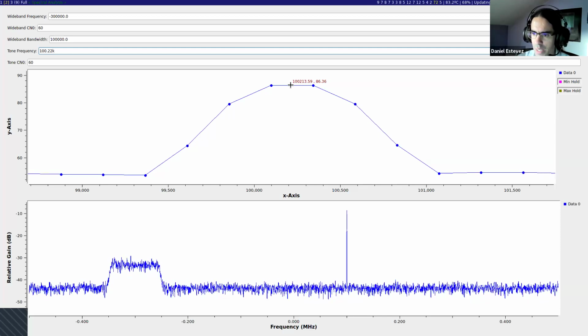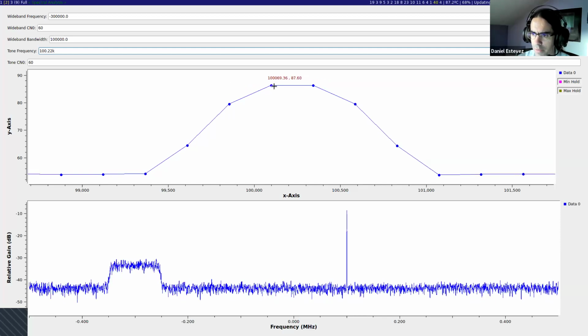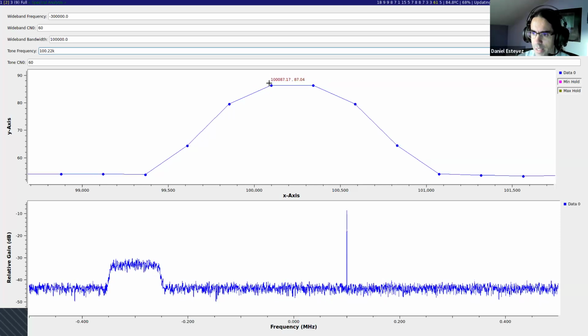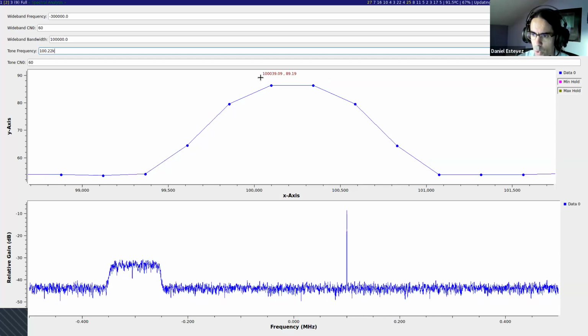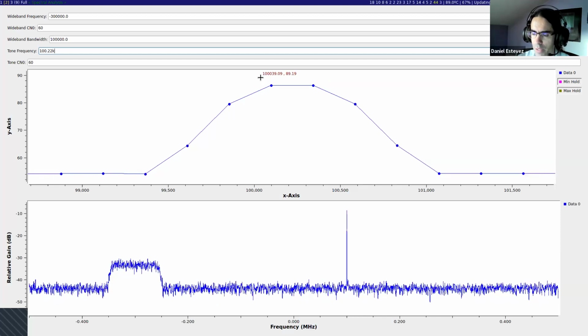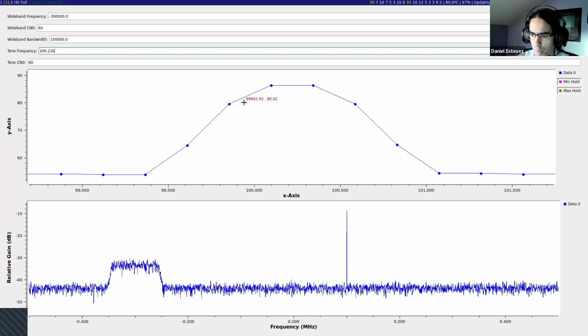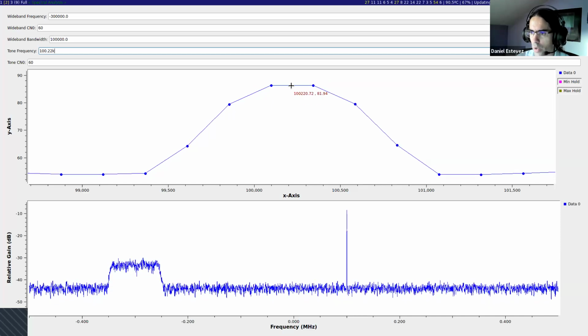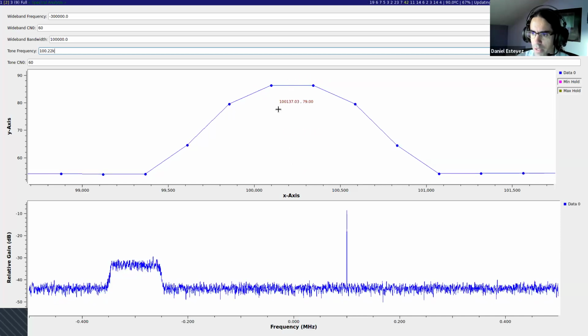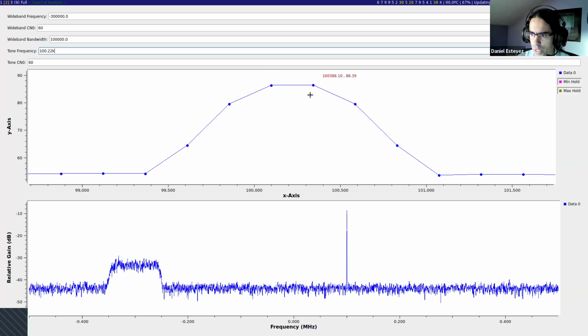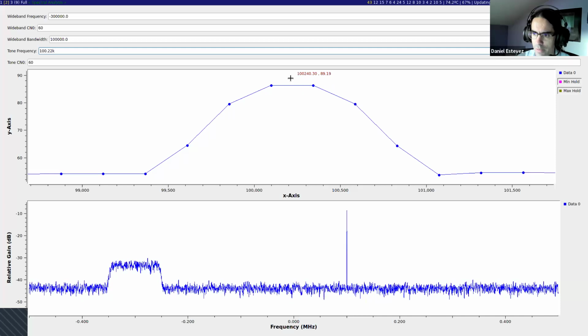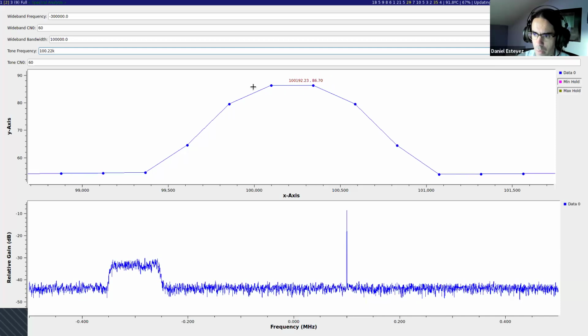And that makes sense because when the FFT bin lines up exactly with the signal frequency, then the signal falls exactly on top of the thing we are measuring with the FFT, and we get all the power of the signal there. When the signal falls in between two FFT bins, the power is divided between two adjacent FFT bins, and so we have a small reduction in the power we see.